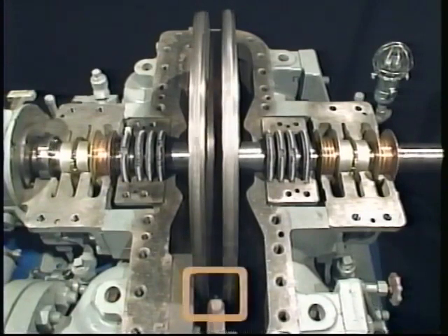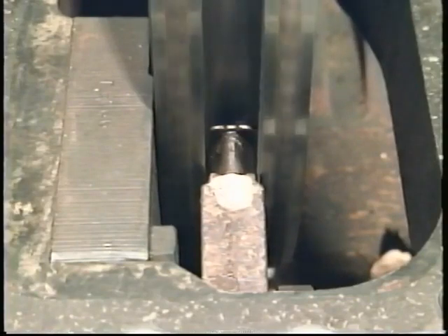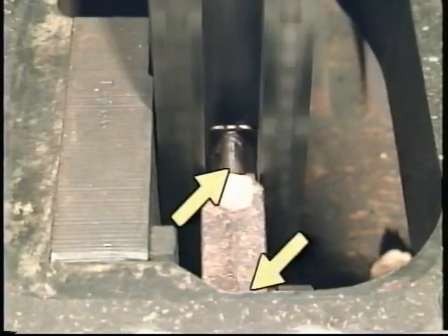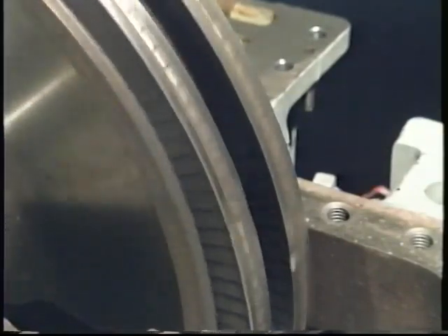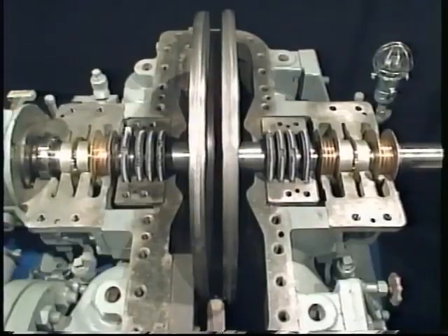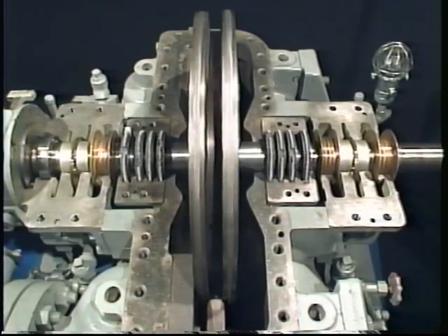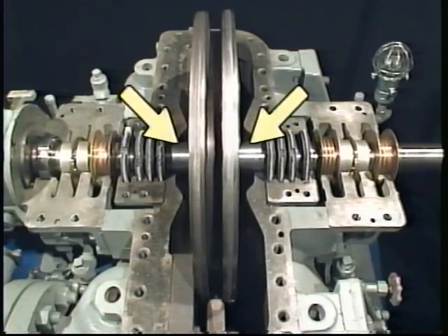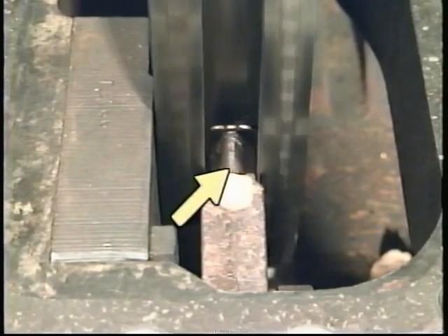Turbines also have blading that does not rotate. There are a series of fixed or stationary blades here, attached inside the bottom half of the casing. Both kinds of blading, fixed and moving, work together to accomplish the energy conversion that takes place in the turbine. This example shows the blading arrangement in a typical small turbine. Two sets of moving blades are included on one wheel that is attached to the turbine shaft. The fixed blades here are located between the two sets of moving blades.